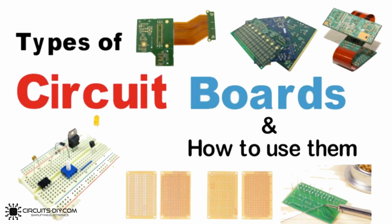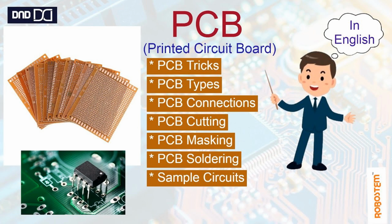Metal core PCBs, MCPCBs. In some applications where efficient heat dissipation is critical, such as LED lighting and high-power electronics, the substrate may consist of a metal core, typically aluminum or copper. This metal core helps spread and dissipate heat more effectively. Ceramic substrates. Ceramic materials, like aluminum oxide, Al2O3, and aluminum nitride, AlN, are used in specialized applications where excellent electrical insulation and thermal conductivity are required, such as in high-frequency RF circuits or power electronics.